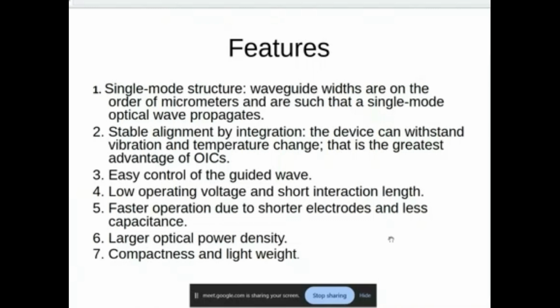But design is very convenient, and the devices are very compact, very small. Typically 4 microns is the width of the waveguides that you see around. Fiber optics, you know, is about 9 microns. You can also manipulate the modes, because most of you are from a physics background. You can calculate all the modes of these optical waveguides and then manipulate them. Suppose there are 4 modes in a waveguide. You can exchange power between them. You can redistribute, and so on and so forth.